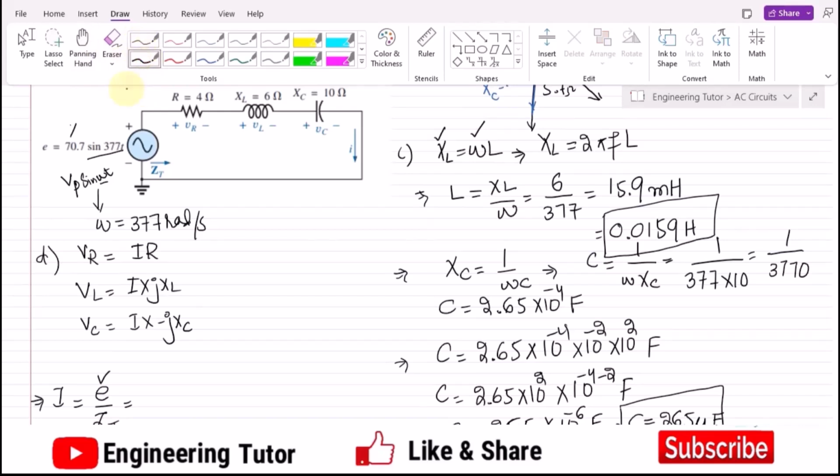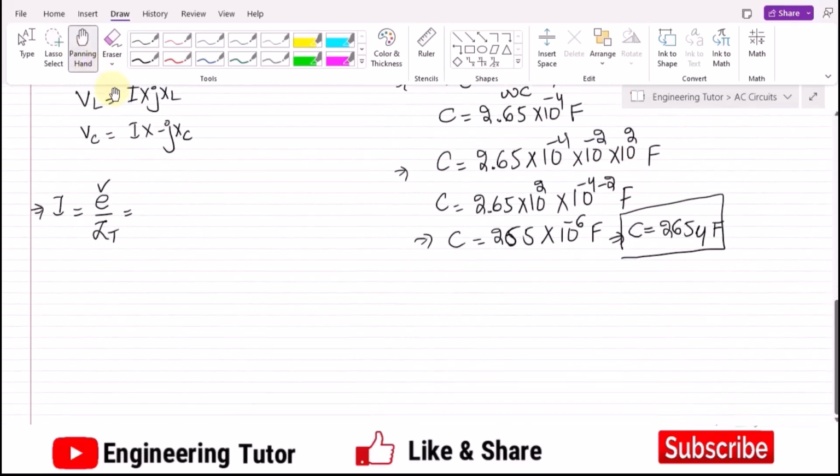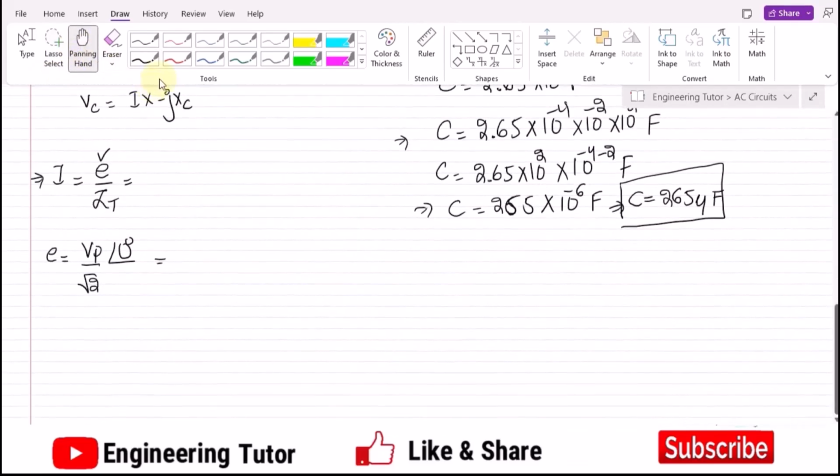We can see that this is the peak value, this is omega, and the angle it has is basically 0 degrees. So this VP should be converted into the VRMS, and we know that VRMS is equal to VP divided by square root of 2. So now let me calculate the value in phasor form. Here it will be VP divided by square root of 2, and the angle it has is basically 0 degrees. VP is how much? Let me confirm it here. Yes, that is 70.7 volts.